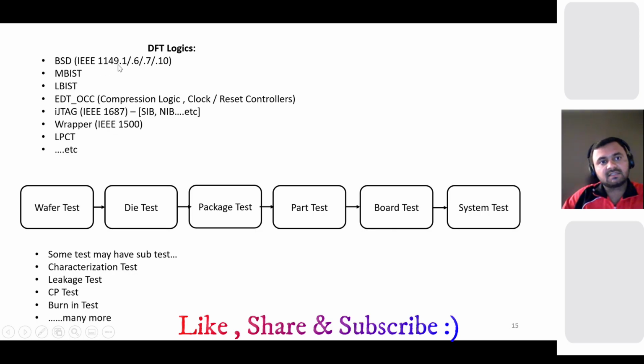1149.1 is, as I told you, for the case where we have two kinds of pads, analog pads and digital pads. Since we have two different signals, analog and digital, we have two types of pad. So 1149.1 is for the digital pad, and 1149.6 is for the analog pad. There are differences in testing, which is why we have different pads, and different ways to handle the signals. Then we have 1149.7 for mixed signal and 1149.10 for high speed. These are the things we use, and a mix of them if we have both.